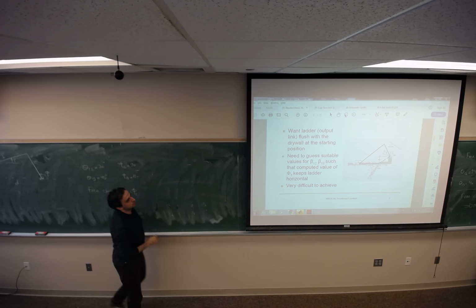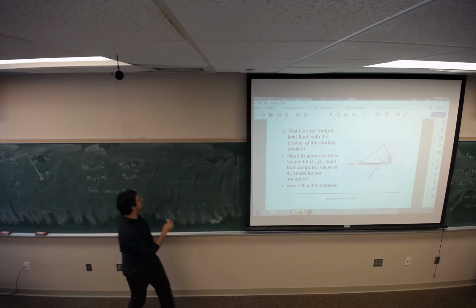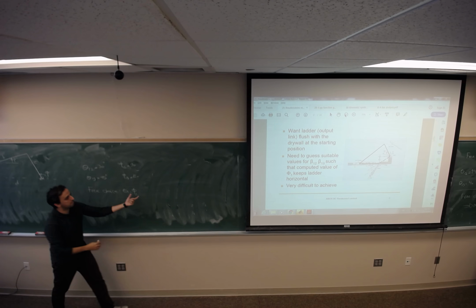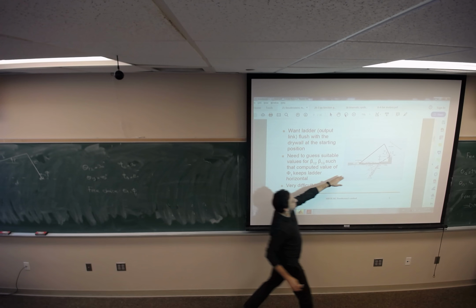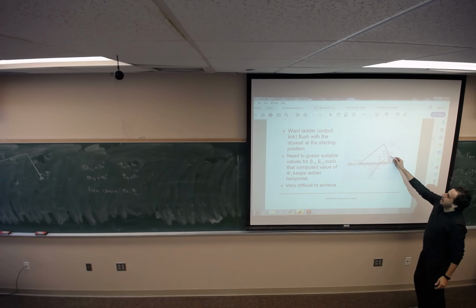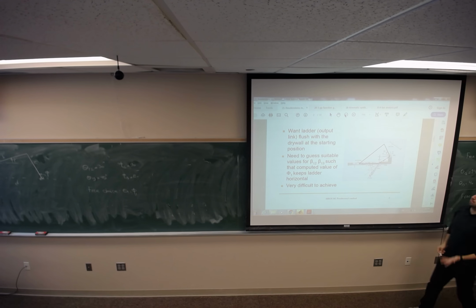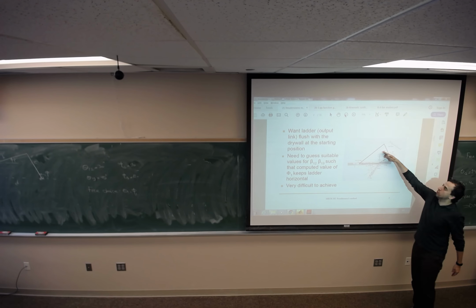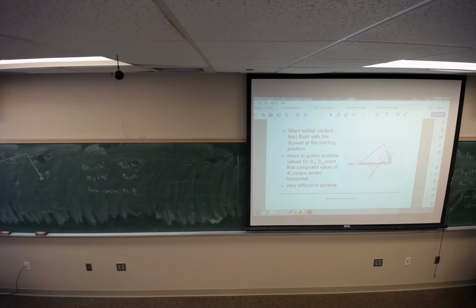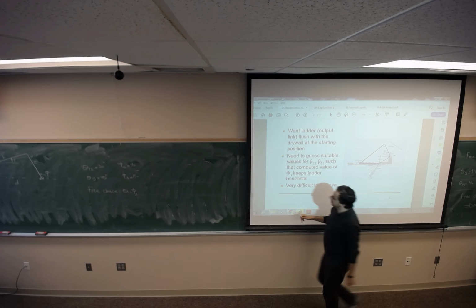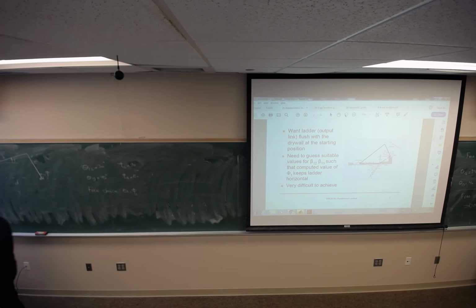We call it the Freudenstein method, and we will see how it works. For this example, I pick phi 1 equal to 180 and theta 1 any angle which is desirable for the design, 20, 25, depending on your constraints. So this is why we introduced the new method.